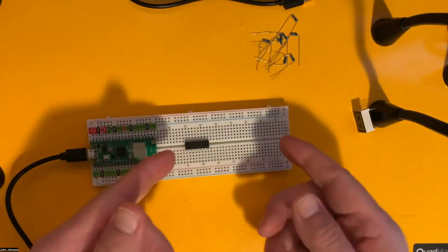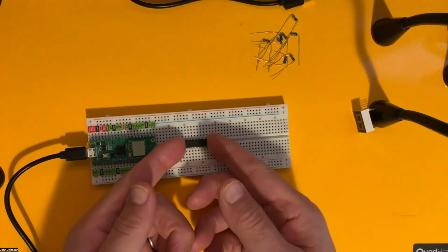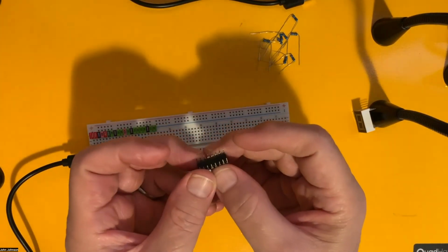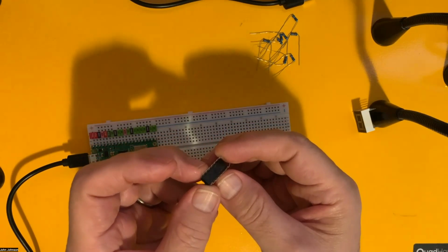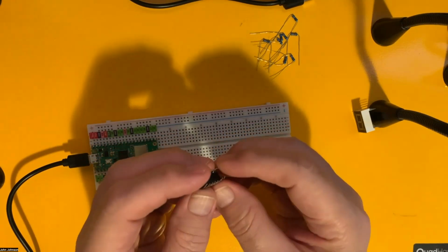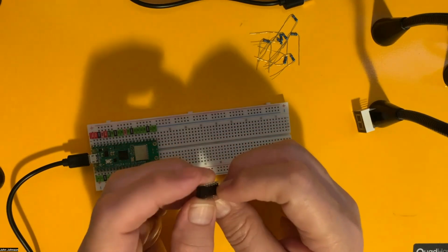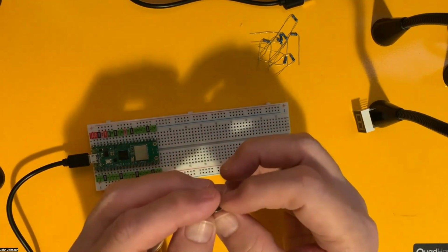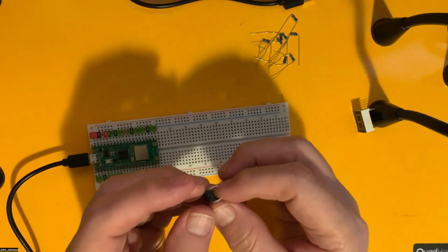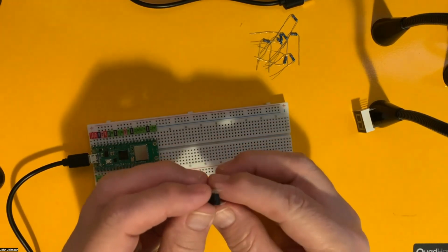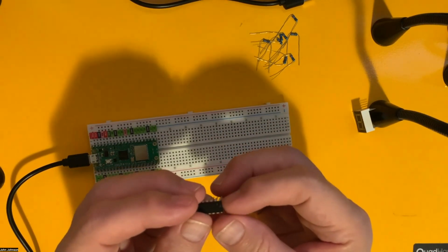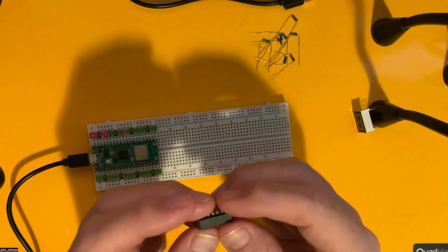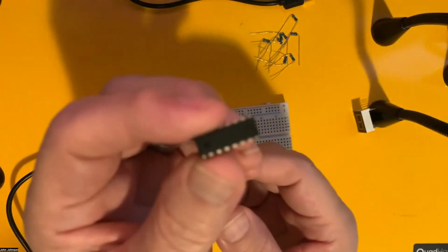So when you're pulling it off, try to pull it as evenly as you can, so that you do as little damage as you can. Look at the pins and make sure they're still okay. You may need to do a little bending here or there to bring them into line when you go to put it in. The danger is, if you don't have this lined up, you can smash a pin, and one pin will easily fold in and you won't even know it. So just be very careful.